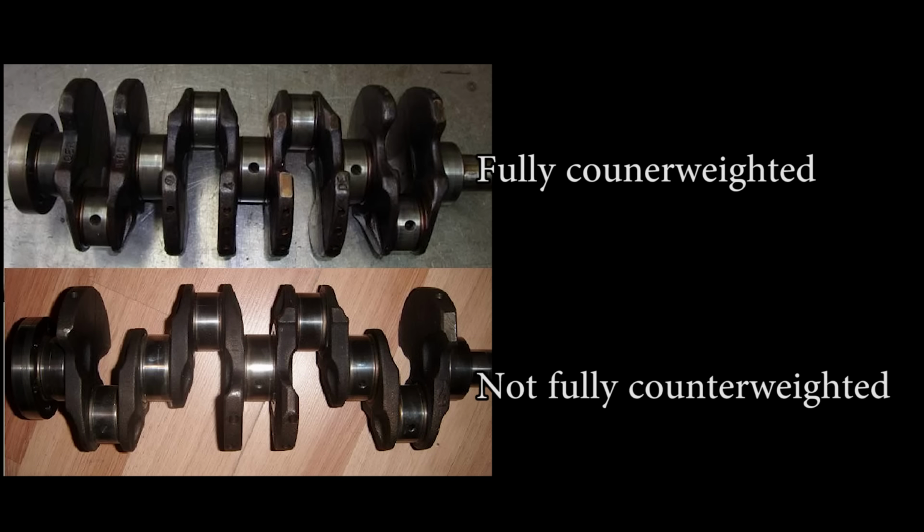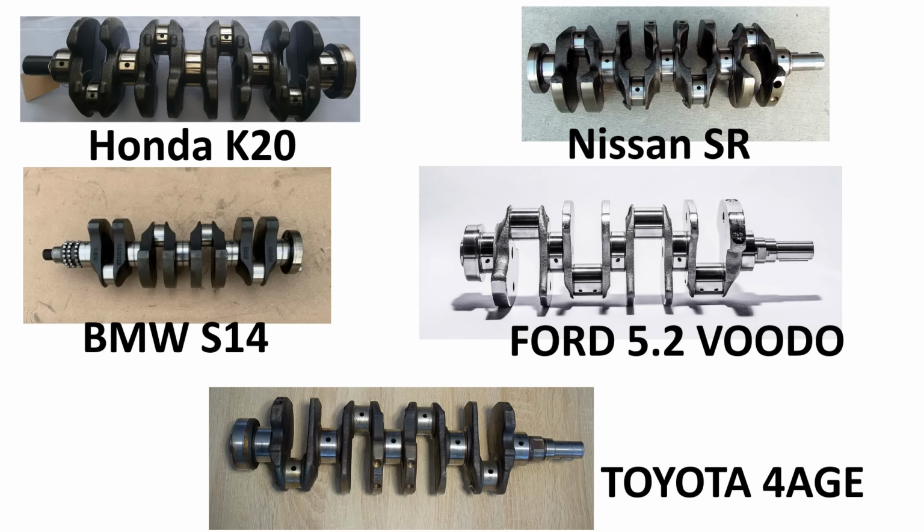A fully counterweighted crank is often seen as a superior crankshaft to a partially counterweighted one. It ensures a smoother running engine and a better ability to cope with extended high RPM operation. Engines that come with high redlines from the factory almost always have fully counterweighted cranks.